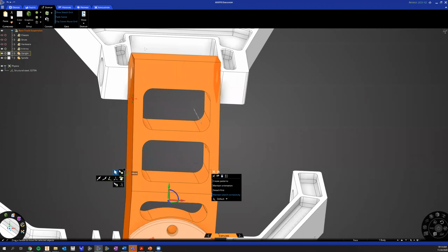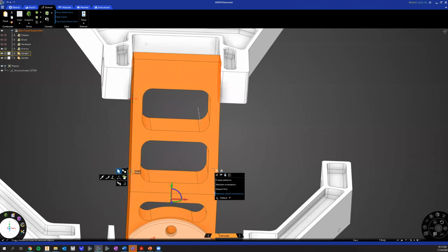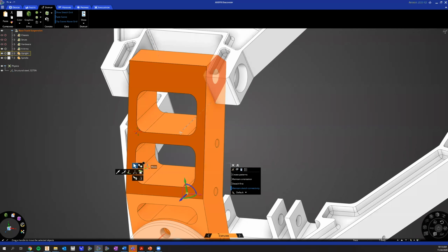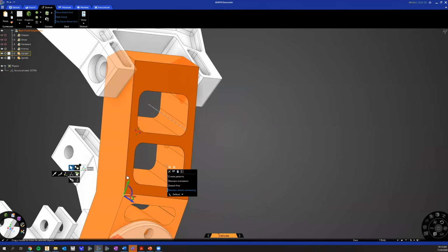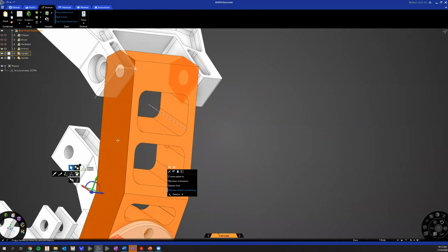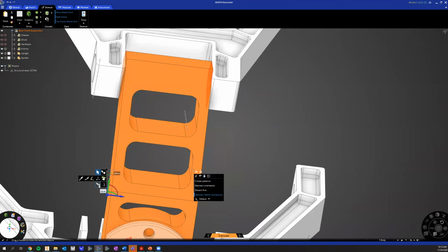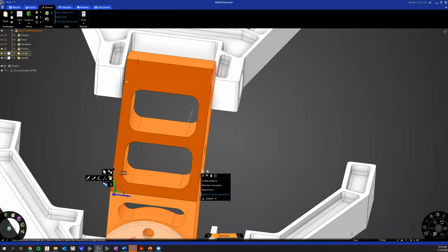And I want it to be coincident with this surface over here on the top A arm. So what I'm going to do is take this yellow ball and move it onto this surface. And now that's where I'm referencing. I'm going to click on the up to capability, where I get to click on a surface I want to move this up to. And I'm going to do this by accident.